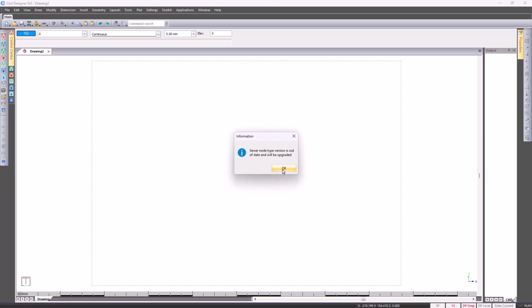During this process, all the node chamber dimensions are automatically assigned to the nodes based on the node type. If there was a node that had manually specified chamber dimensions and those dimensions were different to the node type defaults, then that node type is upgraded to auto sizing. The auto sizing is based on incoming and outgoing links.